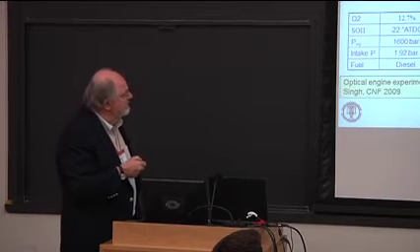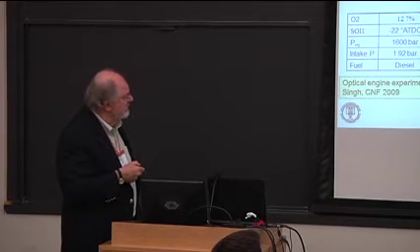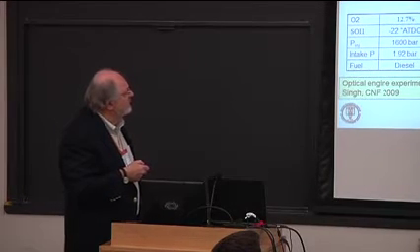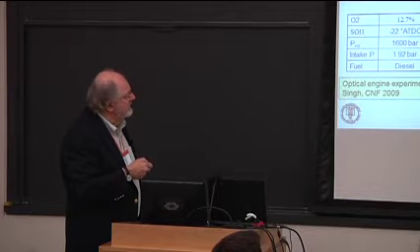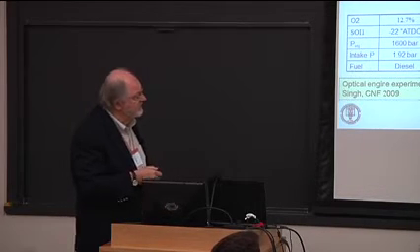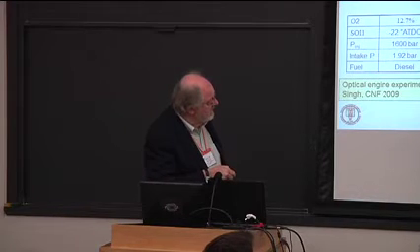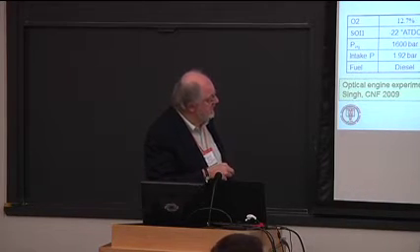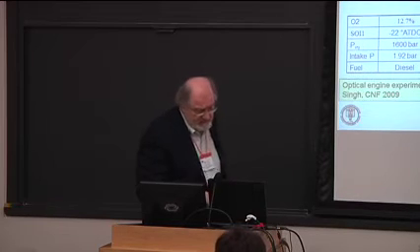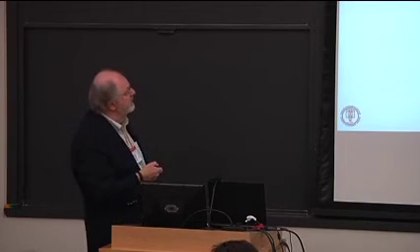Very consistent with Mark Musculus's conceptual model, where again, we said you could identify the first stage and the second stage combustion, and then the soot forming regions. And you can even see those soot regions associated with this vortex at the tip of the jet, just like in the model. So just to summarize then, what we see is that the flame structure really depends on how much time is available for mixing.